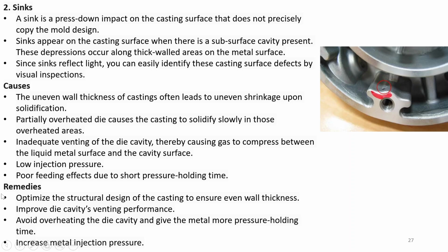Now, this can be prevented by optimization of the structural design of the casting to ensure even wall thickness, or improvement in die cavity venting performance. Avoid overheating the die cavity and give the metal more pressure holding time, and increase the metal injection pressure.